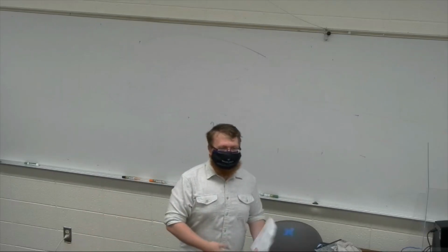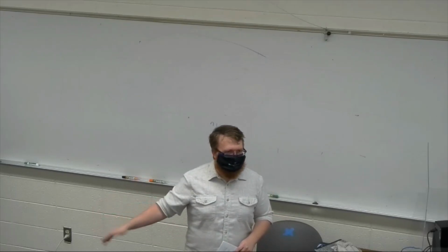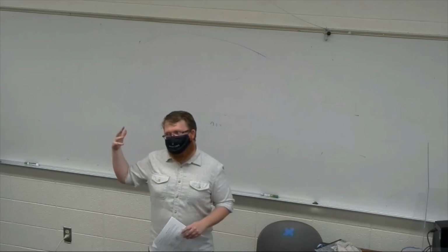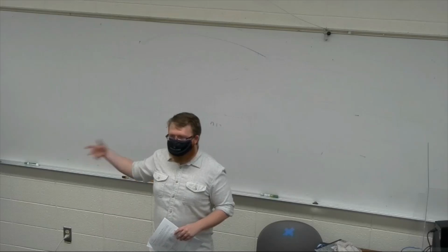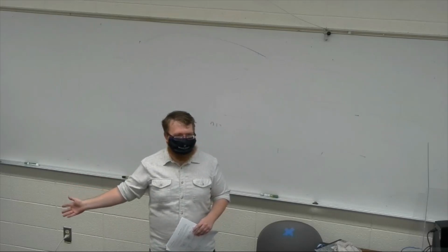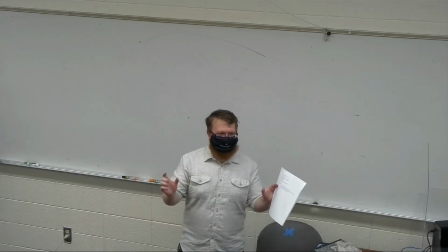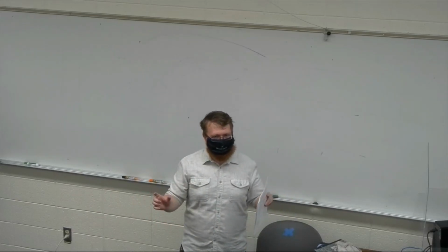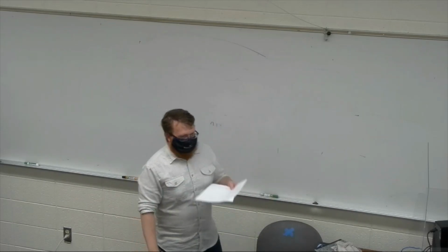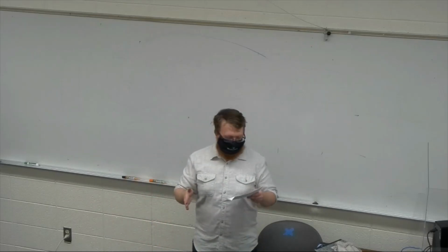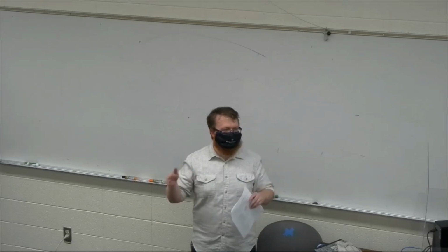There was another hint in that I said there was 1 packet at t equals 0 and 1 packet at t equals 1 second. That's a hint that nothing happens for a really long time, so the second packet doesn't actually come into play at all. I was also a little bit nice in that the first packet started and ended with a 0 to make it more obvious. Apparently that didn't help. The issue is, if you look at stop bit, you enter stop bit at 1/4 of baud through the last bit in the byte.